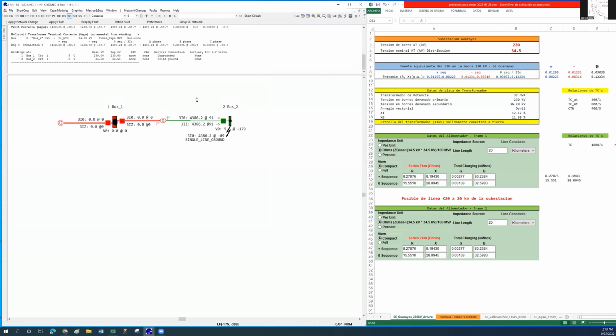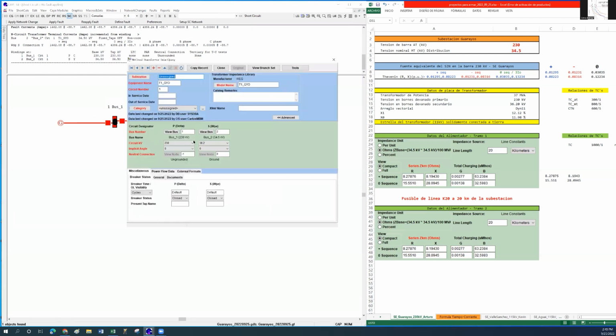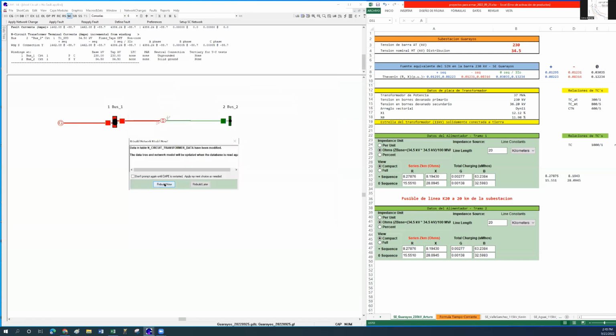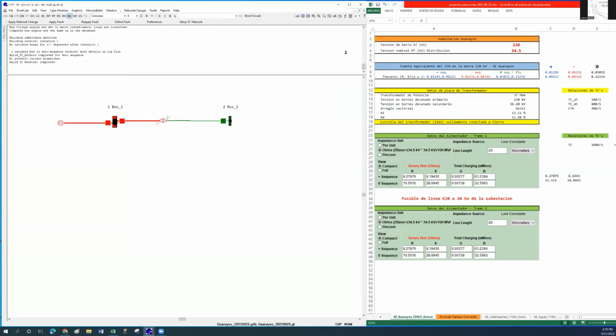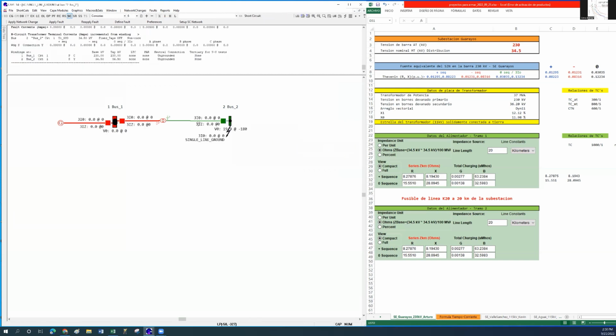I'm going to clear all the faults now. Let's take a look at what would have happened if I had forgotten to do the grounding, and left this field as -1. Now let's run a ground fault simulation. Right-click on the bus, select faults, and then single line to ground. We can see there is no zero sequence current and no fault current at all.